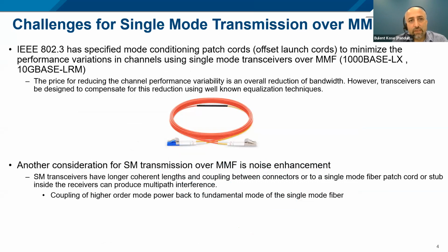Another point: 802.3 has specified mode conditioning patch cords for offset launch to use single mode over multimode.